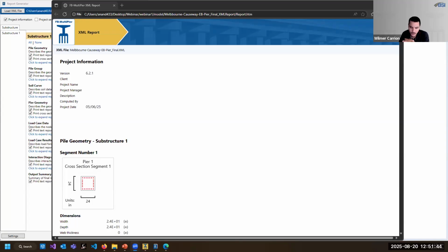And also if they have a bent cap with a small 3-inch gap and they only want to model half of the cap with half of the bearings, how should they adjust the wind loads to reflect the actual wind load on half of the bearings? So it sounds like they want to model only half of the model, and how do they account for that.